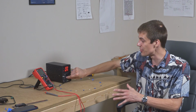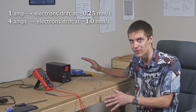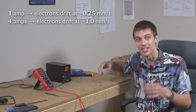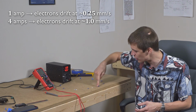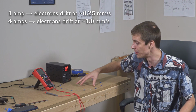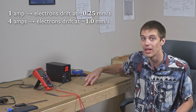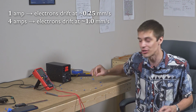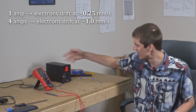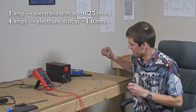Now, if I increase the current flowing through this wire, now we have roughly 4 amps flowing through this wire. That means that the average speed of an electron chugging its way around this wire is about 1 millimeter per second. The drift velocity of the electrons, the average speed as they move around the loop, is linearly proportional to the current. And now this is starting to smell and smoke, so I'm turning it off.